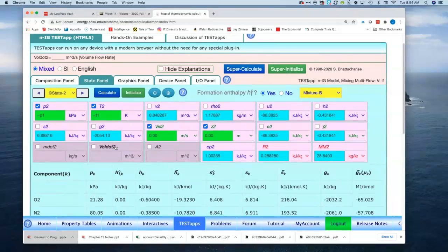In this particular case, it's going to be equal to 1.5 times 2 is 3, and then times the 4.76. This is the total number of moles that correspond to the air, since it's 1 mole of oxygen and 3.76 moles of nitrogen times 2 times 1.5. And so that's where I get this number.